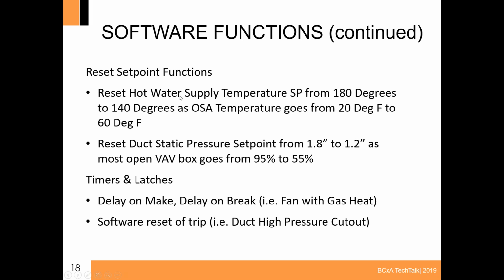Reset functions might be hot water supply. You go from 180 to 140 degrees as the outside air temperature goes from 20 to 60. So you're changing a set point based on some other parameter. In this case, you're changing the set point of the hot water supply based on the outside air.